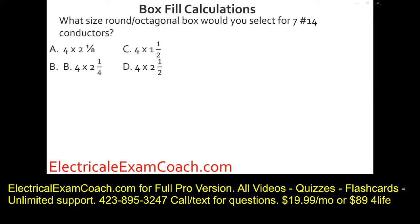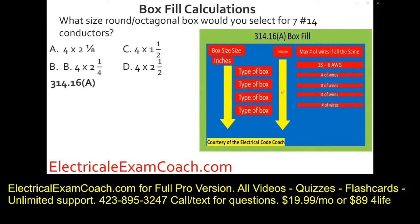What size round octagonal box would you select for 7 14-gauge conductors? We're going to head to table 314.16a. We're going to start here on the right-hand side and we're going to find our gauge wire. Then we're going to come down and find a box that fits it and be sure when we cross over that we stay in the right category of box, and we're going to select C.